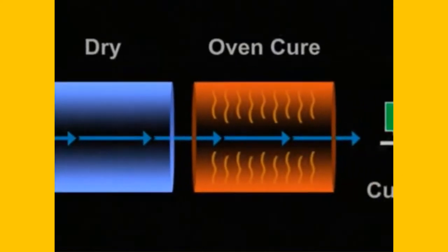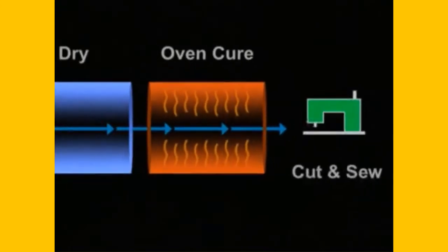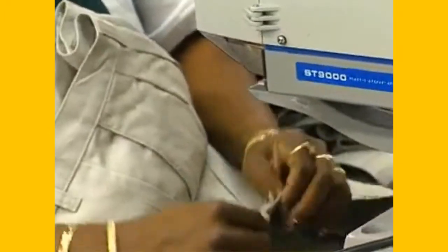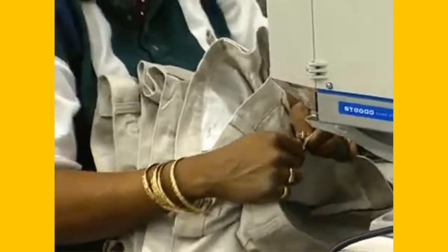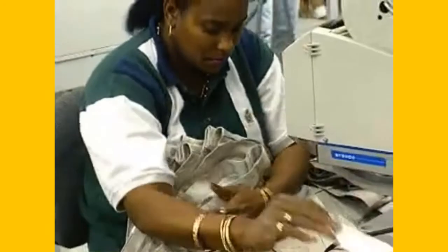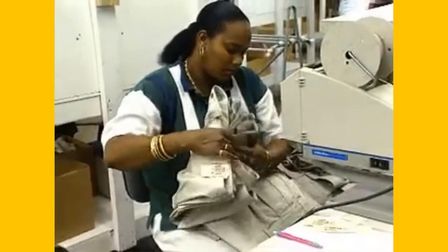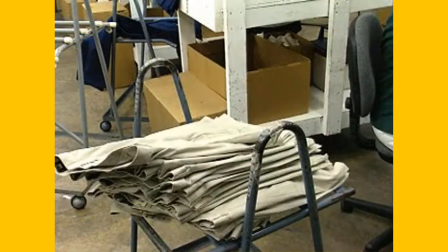After this, the fabric is cut and sewn. The process is quick, inexpensive, and reproducible. Following pre-cure, the garment is assembled and sent to the customer. Almost all shirts and many slacks are made from pre-cured fabric. Because the fabric now has a memory for the flat, smooth state in which it was cured, creases in slacks will not be as durable as those produced by the next process described.